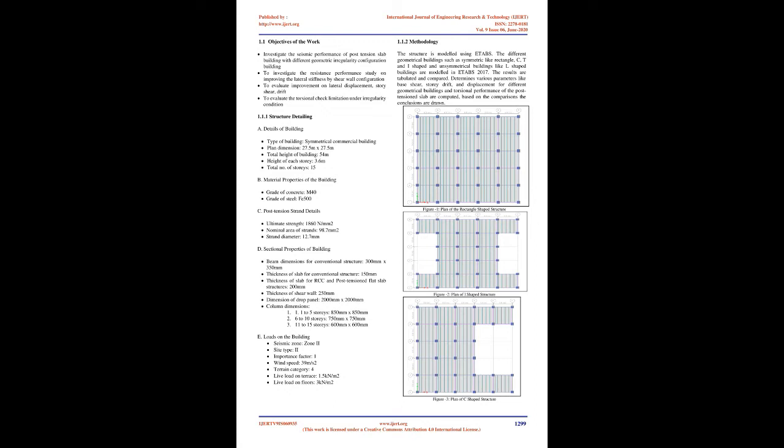3. Poor workmanship can lead to accidents. The main problem with using post-tension slab is that if care is not taken while making it, it can lead to future mishaps. Many a times, ignorant workers do not fill the gaps of the tendons and wiring completely. These gaps cause corrosion of the wires which may break untimely, leading to some untoward events. The post-tension slab is one of the building blocks of the modern architecture, and builders cannot think of making skyscrapers, longer bridges, and marvelous structures without using it.